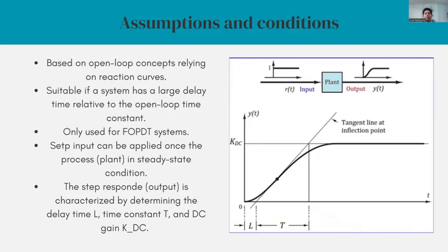Finally, the method was originally developed for non-interactive PID controllers, while it can be adapted to other controller structures such as interactive or parallel algorithms. Adjustments may be required to ensure proper implementation.